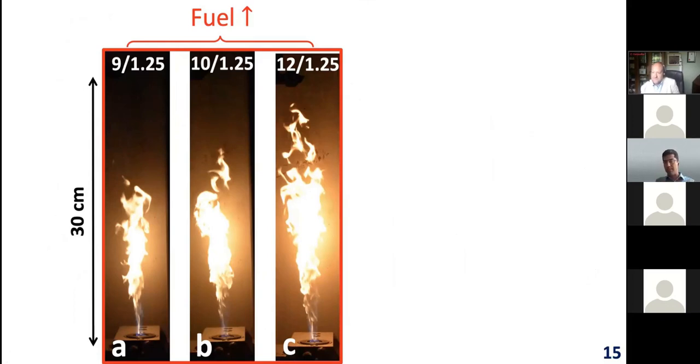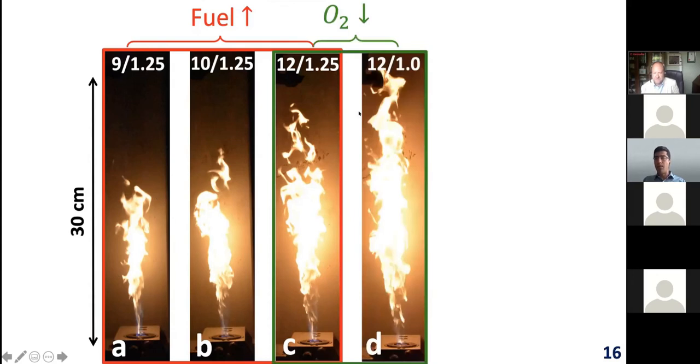Of course, during the SMPS scan, every 5 or 6 scans, I could observe size distributions that had not been fully captured because of the oscillation of the flame. But overall, it was relatively stable. However, if we go to larger flames, or if we put the sampling probe inside the flame, then the oscillation was more pronounced. One way to avoid that would be to sample the particles in a tank and then take the particles from there for the characterization instrument.